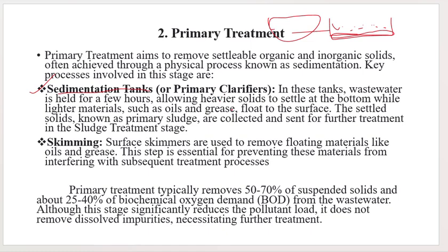What is in this tank? Wastewater is held for a few hours so that the settleable organic and inorganic solids can settle down to the bottom of the tank. The other materials which are lighter, such as oils and grease, will not settle down to the bottom of the tank. They will be floating on the surface of the water.